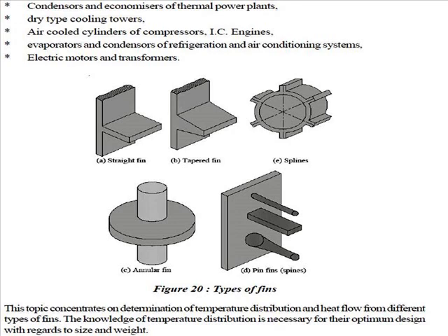Common applications are cooling of electronic components, condenser and economizer of thermal power plant, dry type cooling towers, air cooled cylinders of compressor as well as of IC engine, evaporators and condensers of refrigeration and air conditioning systems, electric motors and transformers, etc. These are some applications where extended surfaces or fins are used to enhance heat transfer.